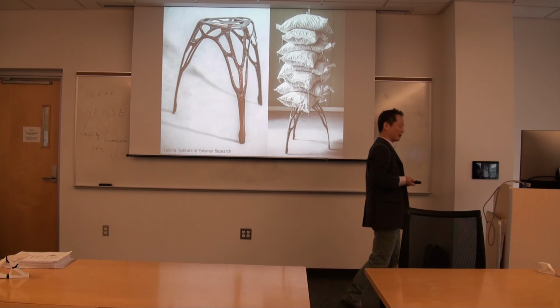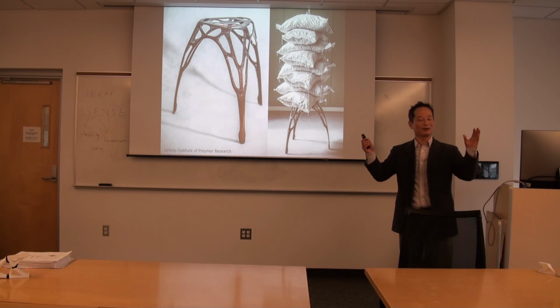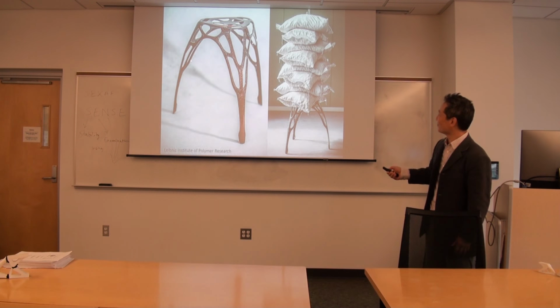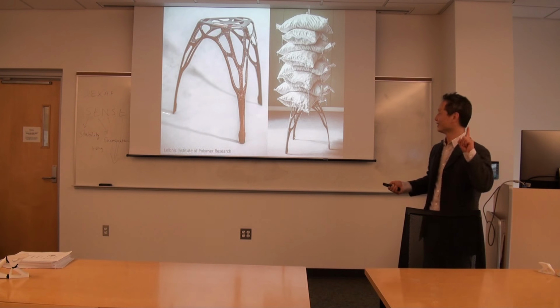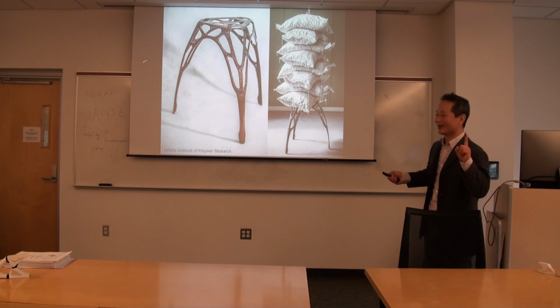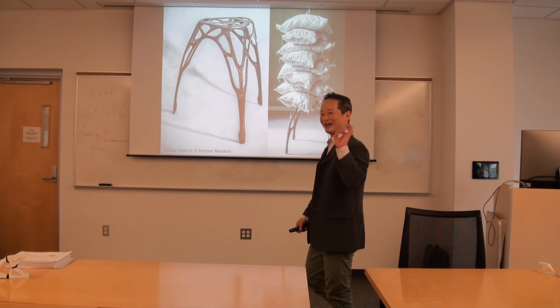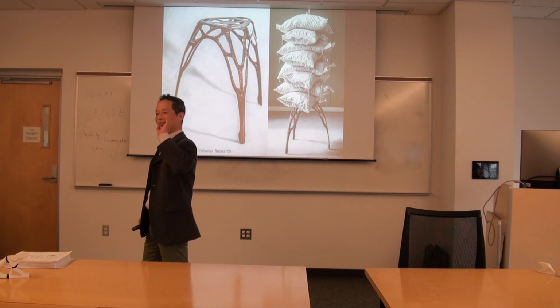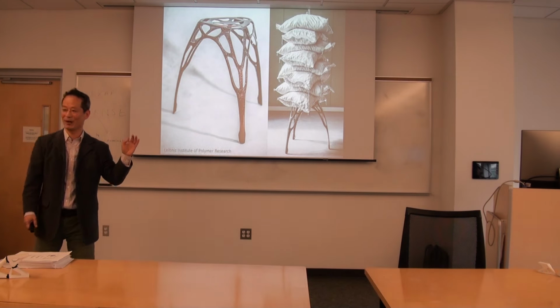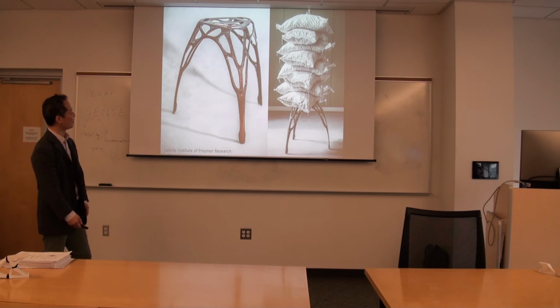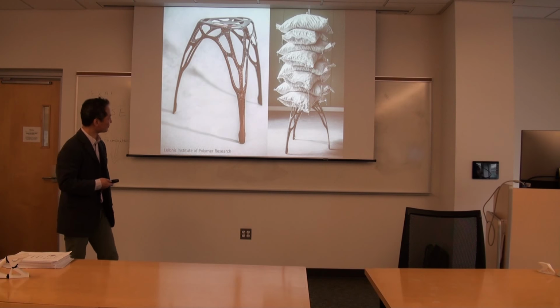And that's the process we are looking at, where we want to apply our method. It looks like one piece. Where is the component? Well, it's fiber branching, really. This particular path of fiber is one component, and another path is another component. And that is the principle by which we apply our MTO, trying to figure out a multi-path fiber layer problem for high performance composites like this, which is probably about to come out in a few months.